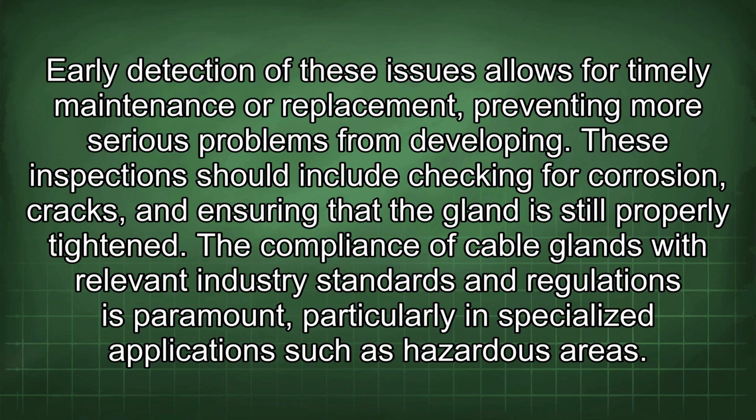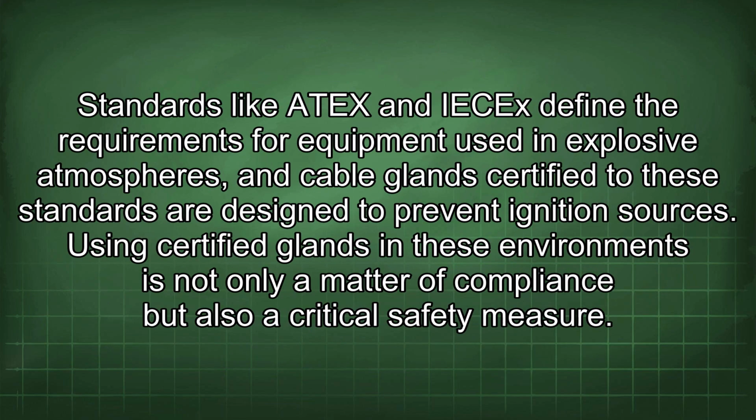The compliance of cable glands with relevant industry standards and regulations is paramount, particularly in specialized applications such as hazardous areas. Standards like ATEX and IECEx define the requirements for equipment used in explosive atmospheres, and cable glands certified to these standards are designed to prevent ignition sources. Using certified glands in these environments is not only a matter of compliance but also a critical safety measure.